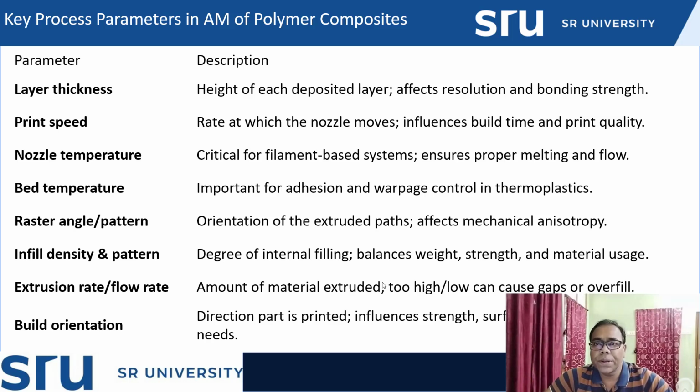So nozzle temperature is also an important factor. Why? Because suppose you are not achieving the higher temperature required for the material. Sometimes we require a higher melting temperature material. In that case, if your nozzle is not able to achieve that temperature, then how will melting take place of whatever supplied or stock material is there? So melting will not take place.